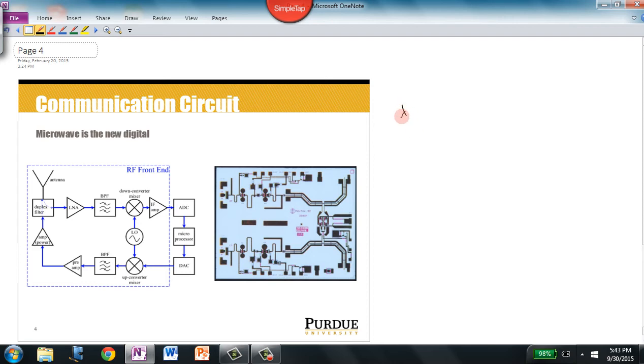If we think about the fact that the lambda, or the wavelength of a frequency traveling in an antenna, is equal to the propagation velocity divided by frequency. Well, let's look at that in free space, because that gives us our worst case scenario. If we were to look at this in free space for microwave frequencies, we take 3 times 10 to the 8th, the speed of light, we divide that by the low end of the microwave frequency, 1 gigahertz, and we get lambda equal to 0.3 of a meter. If we were to do that at the higher end of the microwave frequency band, we take 3 times 10 to the 8th, we divide that by 40 gigahertz, and that gives us 7.5 millimeters.